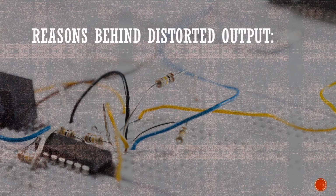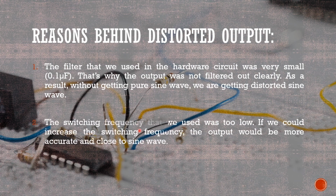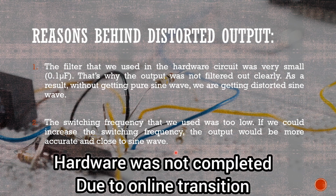There are two reasons behind this. The capacitors we have used are very small. The capacitor is of 0.1 microfarads. That's why the output was not filtered out clearly. Another reason is the switching frequency. The switching frequency we used here was not enough to get a smooth sine wave. Increasing the switching frequency would result in a better sine wave. Our next group members will discuss the software parts one by one.